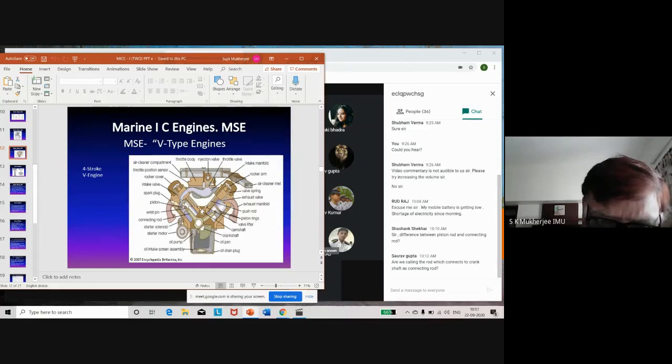So all these three bearings are lubricated, and the oil is ultimately discharged back into the sump. The oil which is splashing inside will splash against the walls of the engine and allow for lubricating of the cylinder liner. The piston has rings. One of the rings is called an oil scraper ring. This oil scraper ring helps to remove excess oil from the cylinder liner.